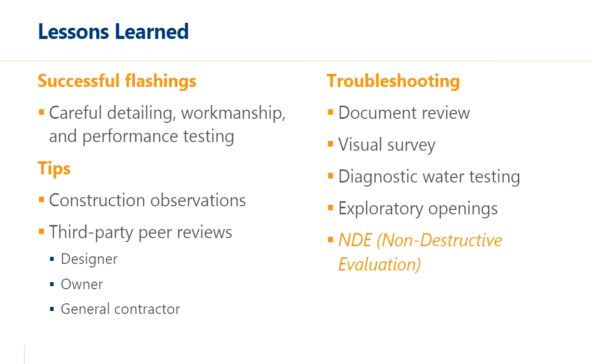Some other quick takeaways, again, to achieve successful flashings, careful detailing and workmanship is needed. And performance testing during the work goes a long way in verifying that the flashings are performing and are watertight as intended, while the cladding hasn't yet been installed, for instance.